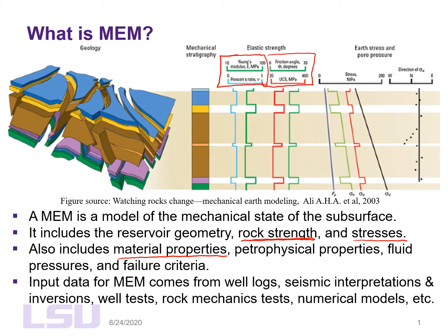The rock strength, UCS, is unconfined compressive strength. So unconfined compressive strength is also in units of megapascals. It's force per unit area. That describes how much stress the rock can withstand before it fractures or gets deformed, before the rock fails. That's the more technical term.